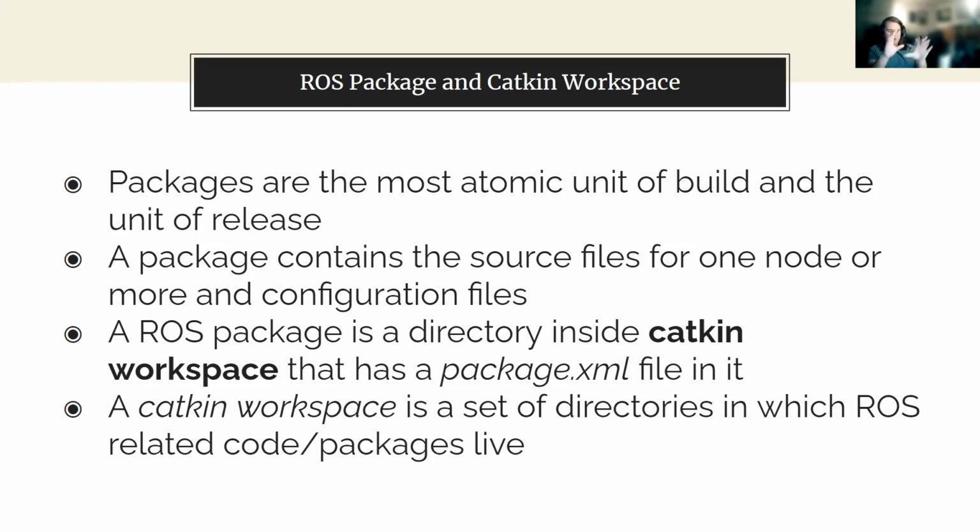So if you have a whole bunch of packages, there's kind of two steps to it. You download the packages, add your code into it if you need it, and then you can do this catkin build that'll build them all and turn them all into executable files or whatever format that you're using. Like Python obviously isn't executable, it's interpreted, but for C++, you need to turn it into an executable file. So it'll figure all that out and do it. And if you have other languages in there, it'll figure that out too and put it into one runnable package for you, which is really nice.